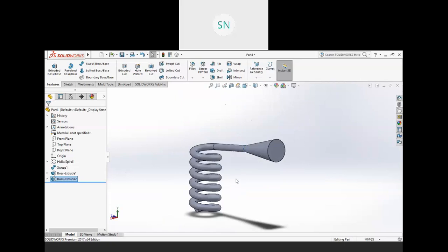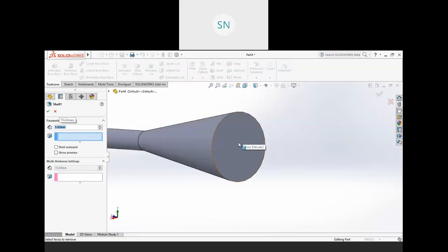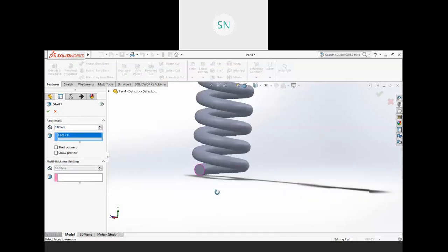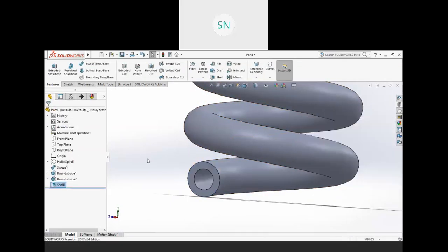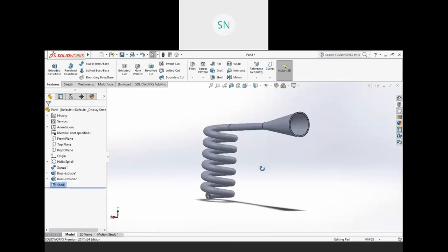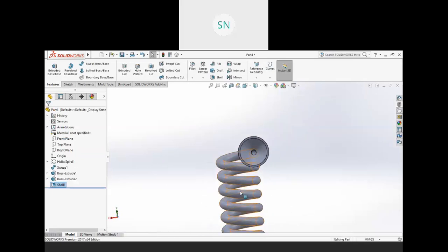So once you create your complete geometry, then at the end you can shell it to convert it into a thickness. Now say 5 mm and I don't need this face, and on the other side I don't need this face. Hit OK. So here we have a continuous shell object.